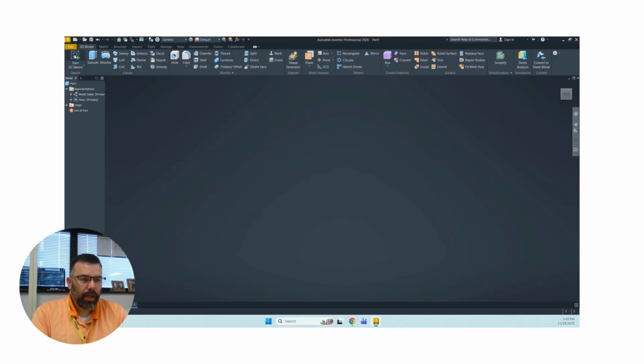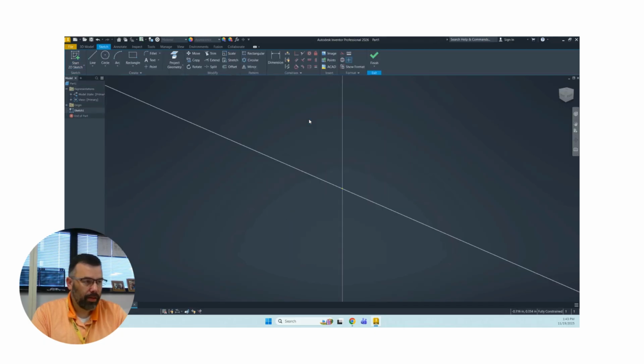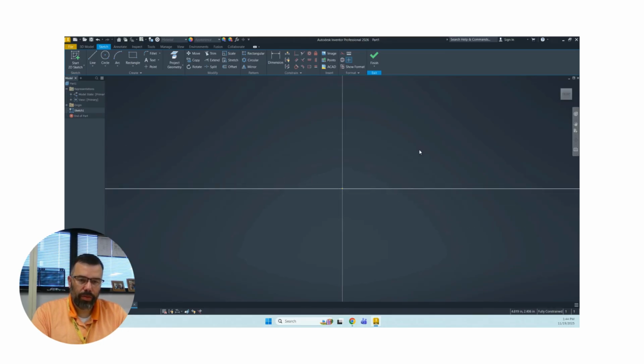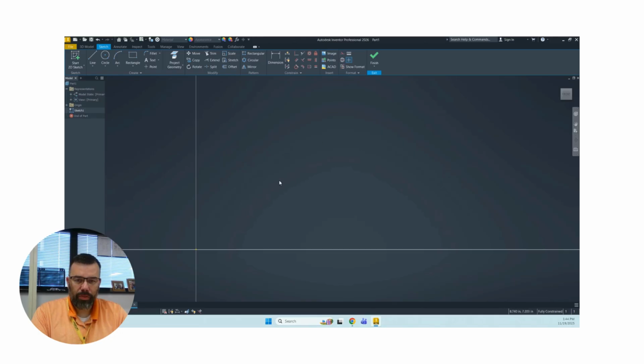So let's start by clicking Start 2D Sketch, and this one I'm going to draw as if I'm looking in from the front. So I'm going to select the XY plane, and then I'm going to click on the front on our little orientation block here, and it will turn so we're looking straight in from the front. And I like to move it over so I'm drawing right in this area here. So let's go ahead and start with the bottom.